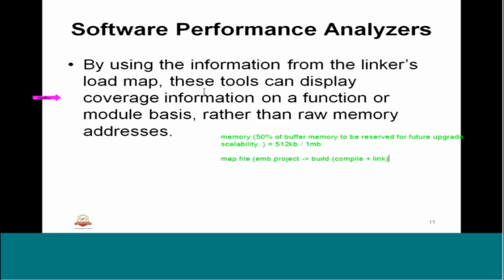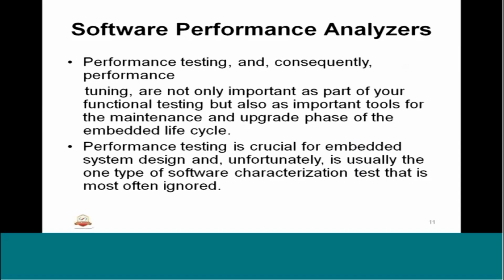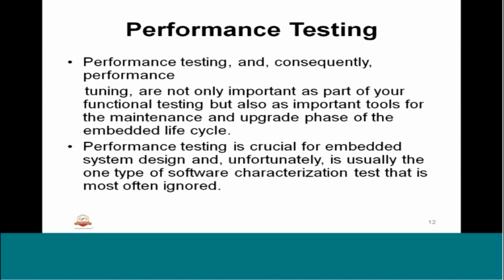With the help of that memory map, we know how much this build is going to take for that particular embedded project, and with that we should be able to arrive at the performance of that particular unit. There are tools and analyzers from different vendors, but mostly it will be done manually or statically.